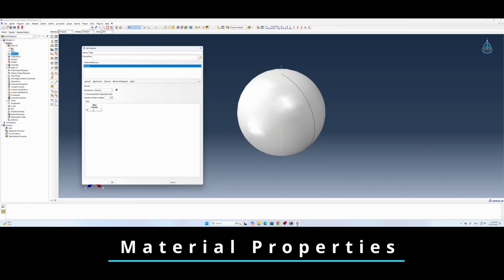So that's why 0.1 gram is going to be 0.0001. After that, we need to define our elastic characteristic. For the Young's modulus, I'm going to use the number for stainless steel, which is 210E3 newtons per square millimeter. For the Poisson's ratio, it's going to be 0.3.